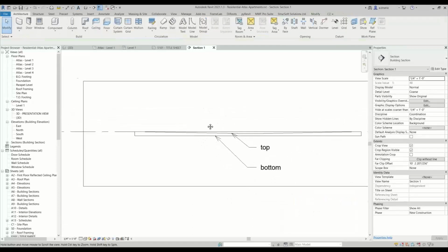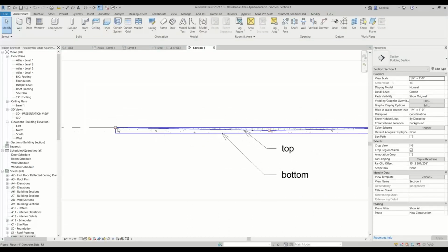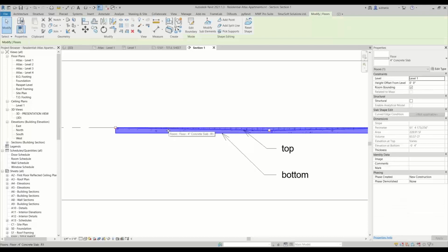So when I'm trying to place my studs, if it's following the top, your studs will be outside your floor, and MWF can't really read that, and it will be like, oh, the studs don't fit, so it's going to error out, right? They don't fit inside the boundary of the floor. So typically we recommend not to do this because the lines are not parallel.